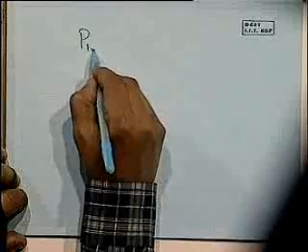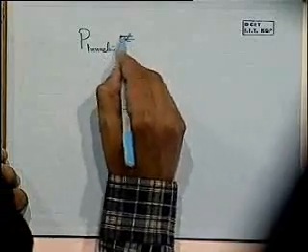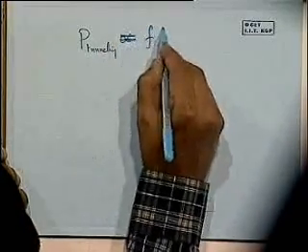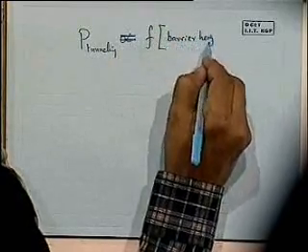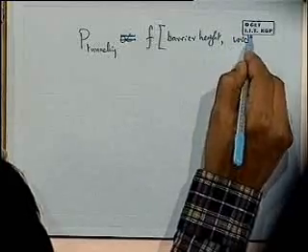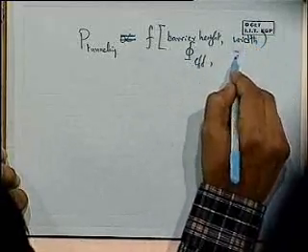To express it simply, the probability of tunneling is proportional to, or is a function of, if you want, I just use the term F, of barrier height and barrier width. So in other words, of phi effective and of xf.